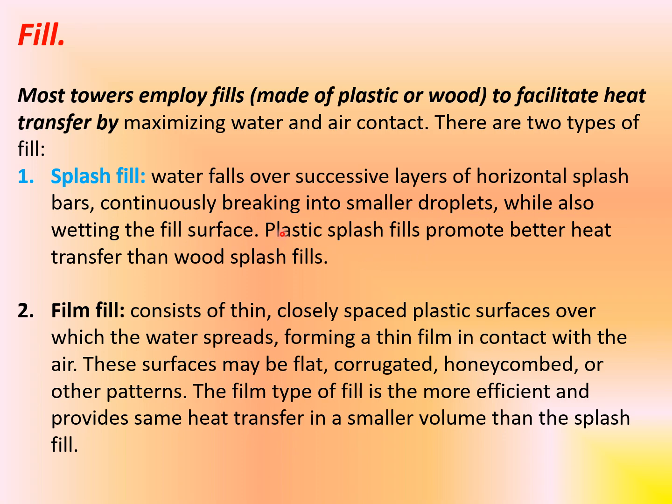Plastic splash fills promote better heat transfer than wood splash fills. Second, film fill consists of thin, closely spaced plastic surfaces over which water spreads, forming a thin film in contact with the air.